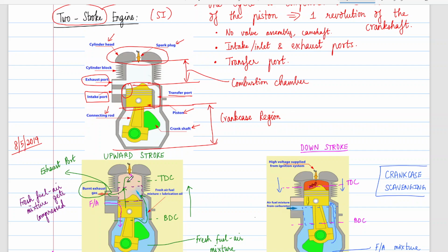All right. So can we manually calculate it? See, manual calculation takes ideal assumptions. So the question is, can we manually calculate the efficiency of an EV gearbox? You need to make measurements in order to calculate. So for example, let's think together. You have a motor, it's connected to a gearbox, and you are getting power out. What I would do is calculate how much power my motor is drawing by measuring my voltage and current at the input side of the motor.